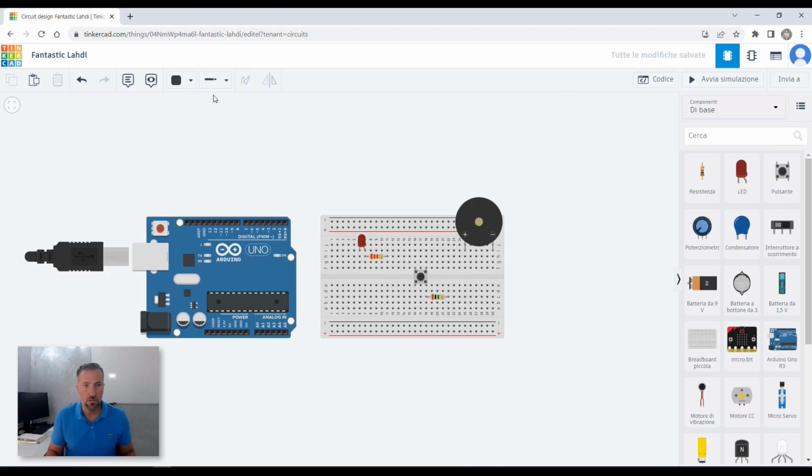So with the components arranged, we first connect the ground on our breadboard. Then we ground the cathode of the LED. We ground one end of the resistor. And we ground the negative of the buzzer. We bring the power supply to the breadboard as well.